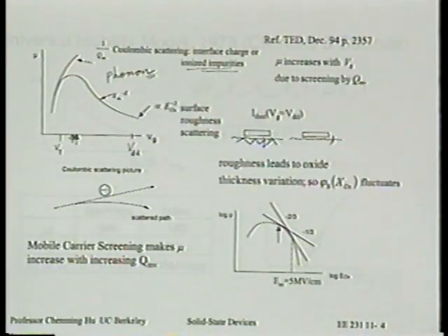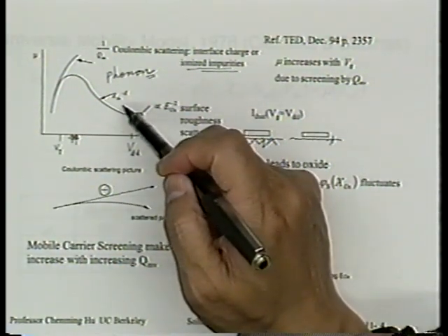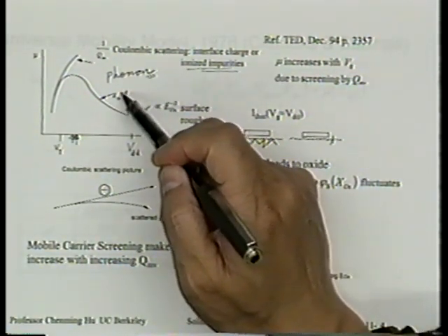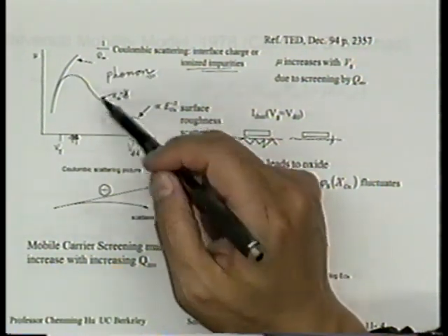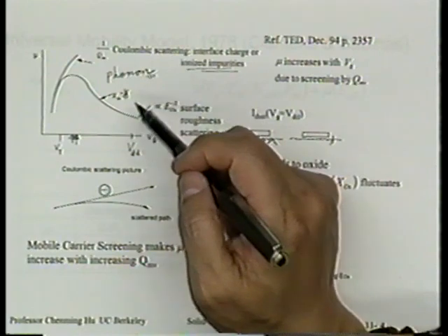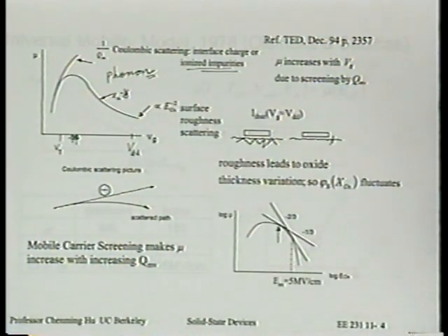So phonon scattering can certainly also decrease with increasing mobility, both experimentally and mainly in some theory, including what I just mentioned about this wave function tailing into the gate dielectric, which actually predicts it proportional to EOX to the minus 1/3 power. And sure enough, if you look in this plot, somewhere you fit E to the minus 1/3 reasonably well. But I don't want to overemphasize that. It doesn't fit over a wide range, all right?